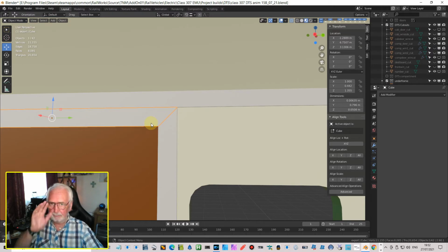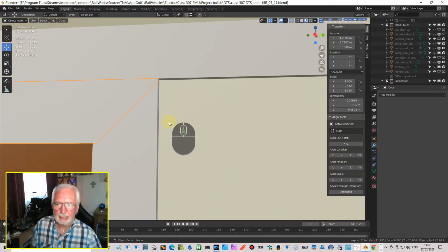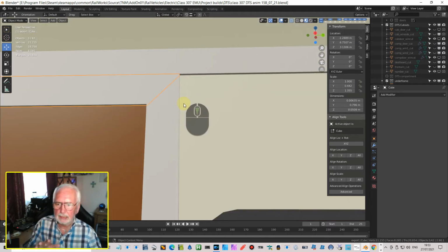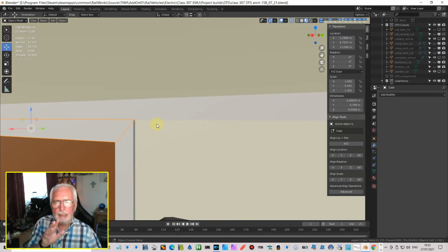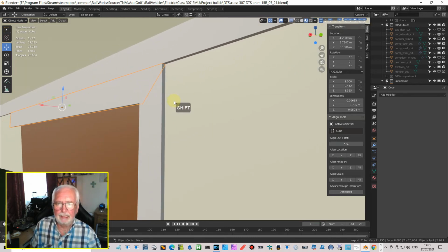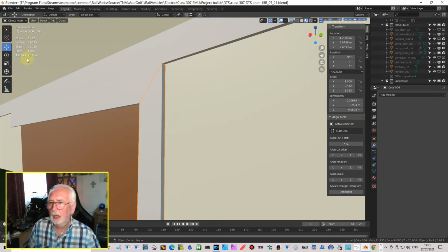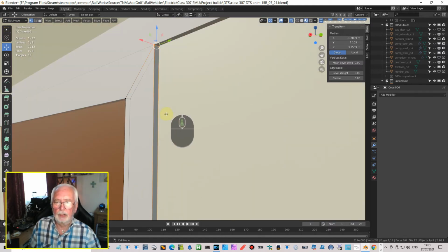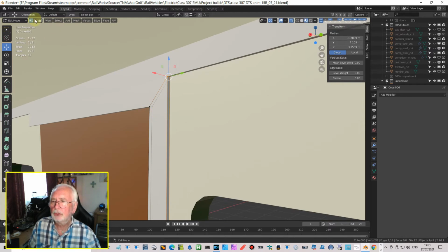in our beading. Okay, now the one thing I want to say here is this is unrealistic to the real world, i.e. these right angles that we've got on our meshes here. You don't tend to get that in the real world. Now the easiest way is to apply a bevel. Okay, and a bevel will soften the edge and give it a more realistic real world look. But if you add bevels, it starts to add to the triangle count. So if I select this one and let me go into edit mode, you'll see at the moment it's 12 triangles. Okay, let me select an edge.